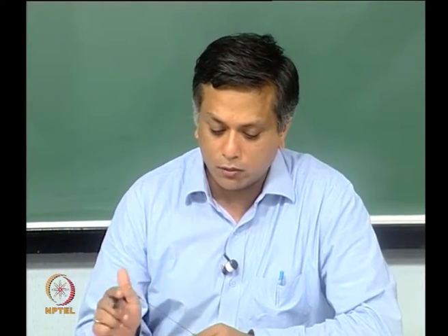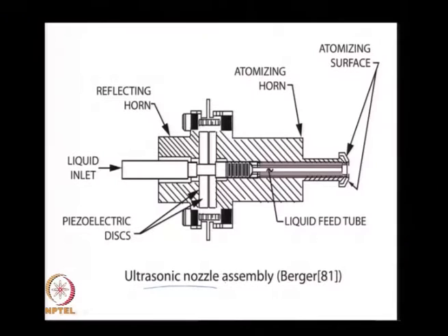Okay. So, if you will imagine an ultrasonic nozzle that has a set of piezoelectric discs around a supply tube. Essentially, what I am doing is I could take this atomizing horn, as it is called, and have it oscillate back and forth in this fashion.